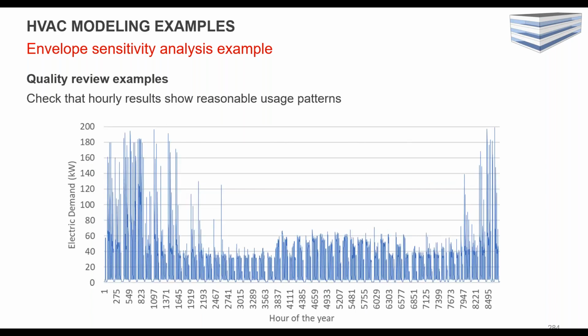You could be looking at hourly. So again, looking at total electric demand and seeing what's happening. And in this case, it's electrically heated, and there's a lot of electric resistance for those heat pumps. So it kind of makes sense that you're peaking out with your electric peak in the wintertime.